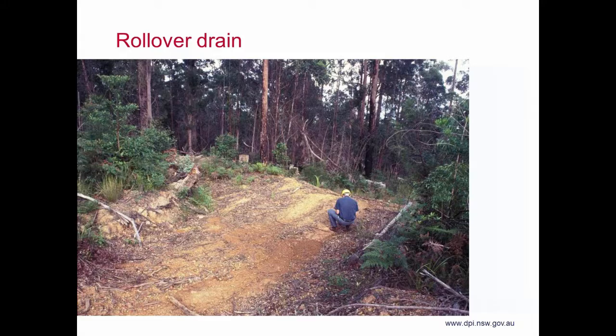Another common type of drain that's used in the next slide is a rollover drain. I'm sure all of you have driven down a steep track in a four-wheel drive and come across these. Usually used on steeper roads and those that are not used that often by heavy traffic, because as you can imagine, a rollover that can be fairly high can be difficult for trucks and so on to pass over, but certainly they're a very effective method on steep tracks of draining the road surface.